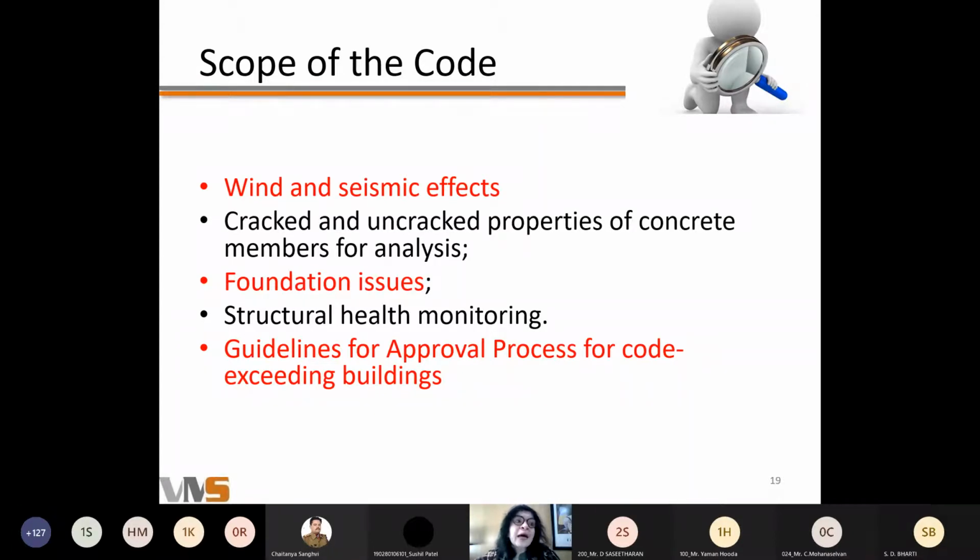Now, despite that, in my own buildings also, I'm not able to get today what is the actual natural period of that building, because there is no health monitoring. We don't put in accelerometers, we don't put in anything. So I think it's time that as a country we build our own independent database, because we build different structures. We cannot compare the database which America has with us, because they have different kinds of buildings. Most of their buildings were in steel. Now they're building some in concrete, but they use very, very slender sections as compared to us. So the kind of data they'll have will be very different from our data.